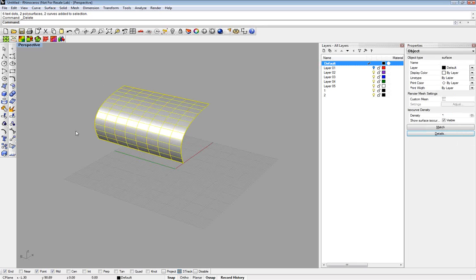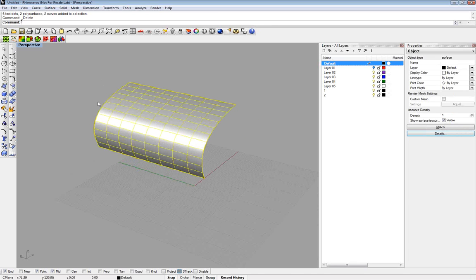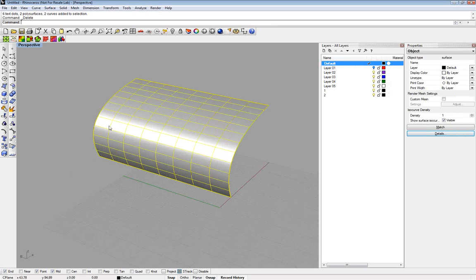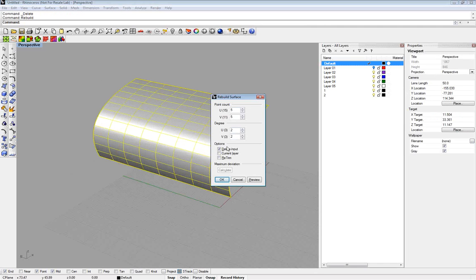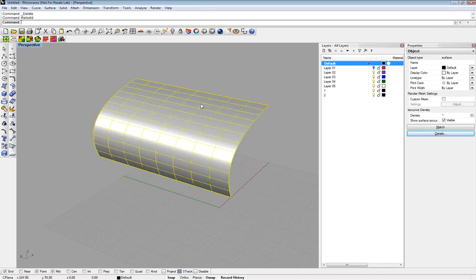Now, when I select a surface, and any surface I generate and rebuild to a situation where the surface is not trimmed, without using this retrim option, it allows me to get this selection directly into Modeler, and get this information using the UV settings of the surface.